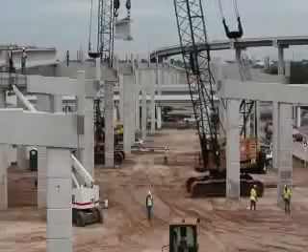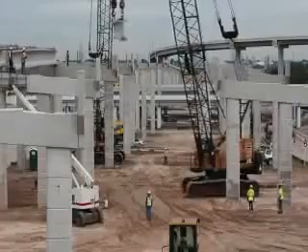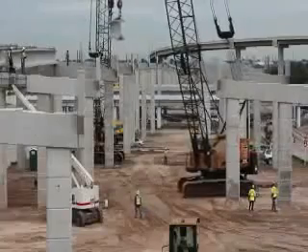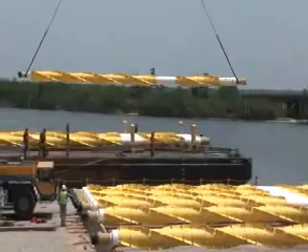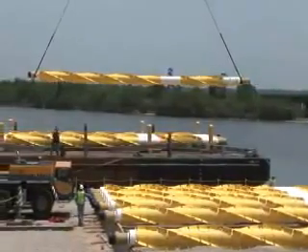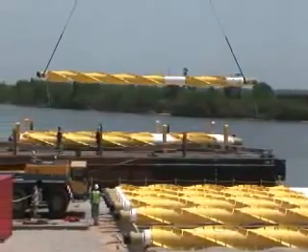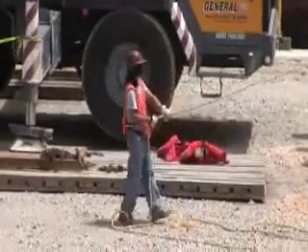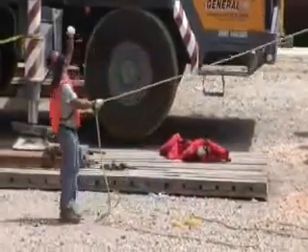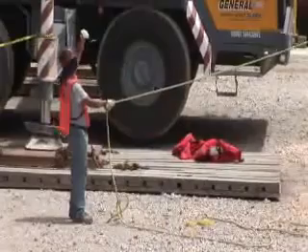Employees can also be struck or crushed by the load as it is being moved. Extreme caution should be used the entire time a lift is being made, and employees should always stay clear of the load. Those workers using tag lines must always stay clear of the load, even as the tag line is being used.